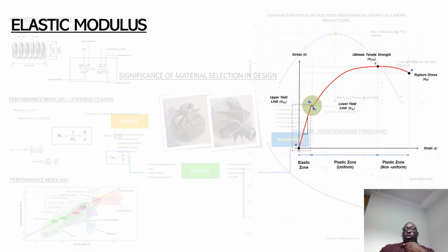So as I've more or less inferred, this can be related to Hooke's law to a certain extent. But this diagram shows a typical characteristic curve for some form of ferrous alloy. So what tends to happen is, if the material is behaving elastically, then you're going to have a linear profile, and the profile will continue to be linear until you get to what's called the yield limit.